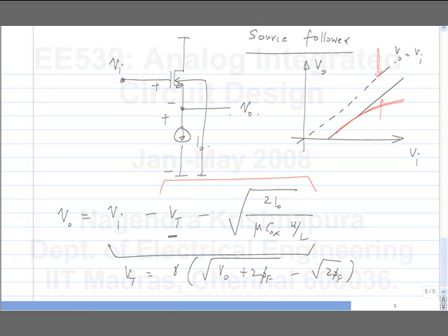This separation now is the Vt plus overdrive, and Vt itself is increasing with V0. Okay. So it gives you first of all a slope that is not 1, right, and the output goes on reducing compared to the ideal source follower output. Is this okay?